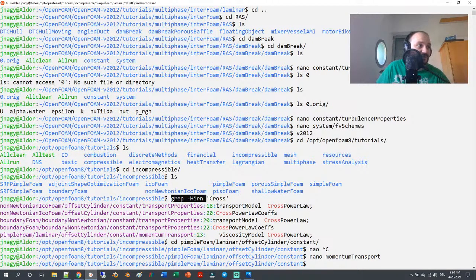K omega is a little bit unstable, is better. Okay, so Nicola just confirmed what I mentioned, and Nicola, you're my man. Exactly, so it is wallDist that you require in fvSchemes for k-omega SST. Do you have any experience in using transition SST? Nope. Unfortunately not. I'm not a very big turbulence properties guy. I just utilize it.